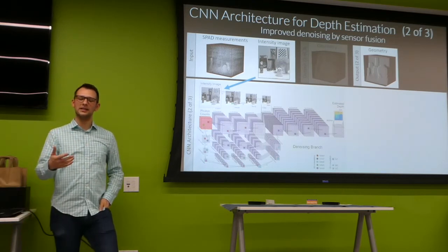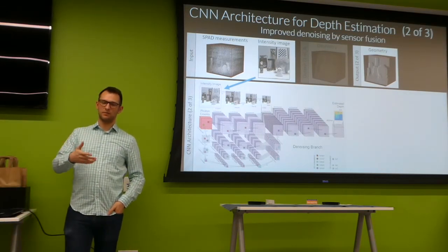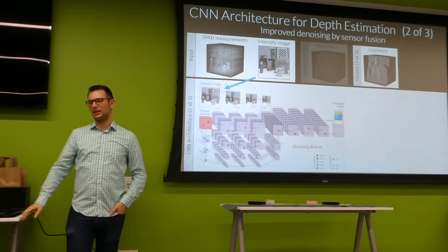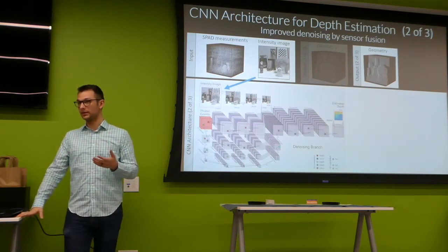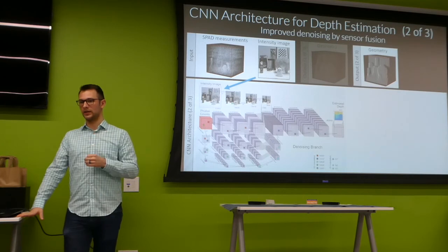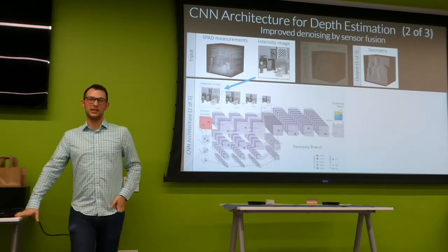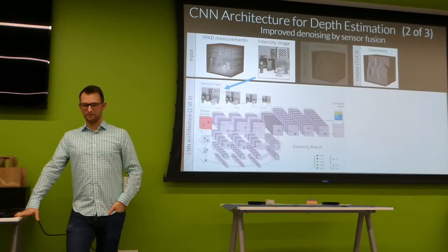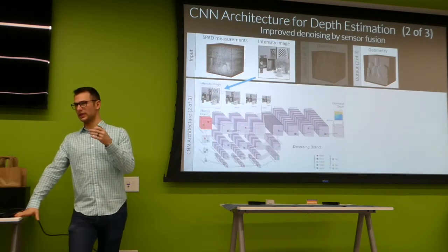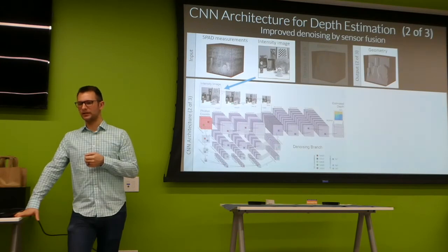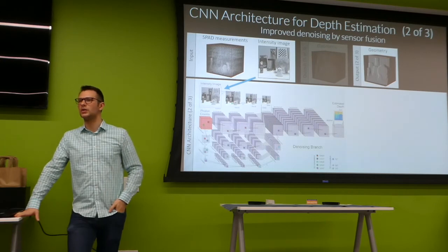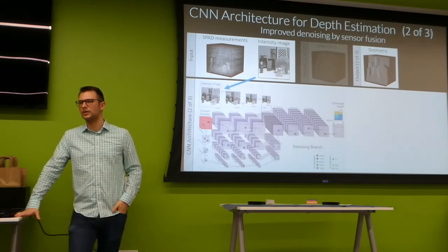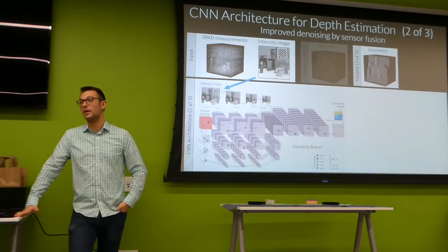These SPAD sensors have a dark count rate, which is basically false detections. The rate for the SPAD array that we had was somewhere in the thousands per second, and for the single pixel it was 40. So it's a big difference in quality. Also, the single pixel was a lot larger, so we got more light. But the SPAD array we had was already a few years old, so I think they've improved on things like fill factor and resolution. So you may be able to do better now.